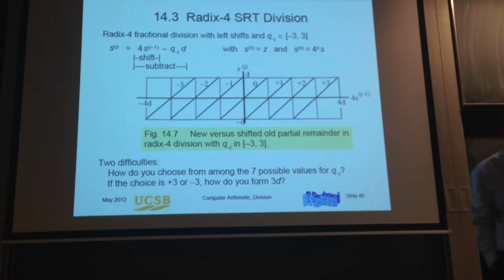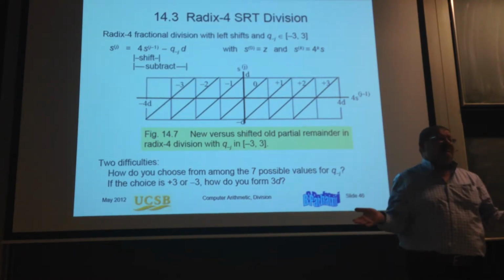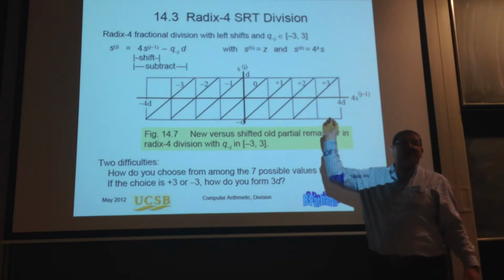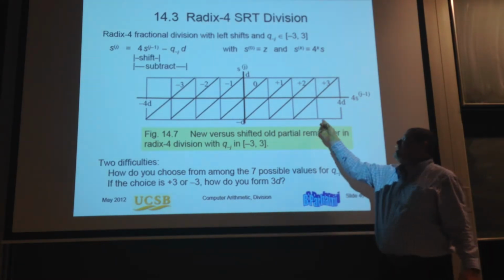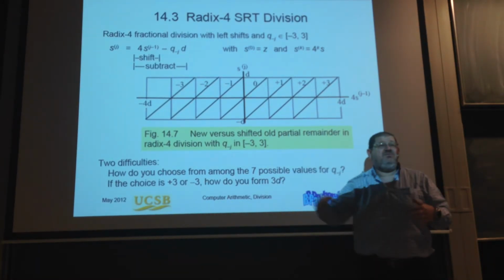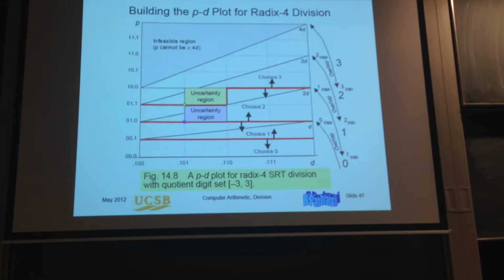We all know the complicated way. And the complicated way, we'll start to compare. Let's say, first of all, I would look if I'm positive or negative. That's easy, it's trivial. Now, depending on where I am, I will start trying to investigate where to go. And I can be optimistic and start from here, or I can start from here, but eventually I may have to do 3 comparisons before I know what the quotient is, and this is forget it. The cycle will explode, and the fact that I'm doing radix 4 will be useless. That's not the thing we'll do.